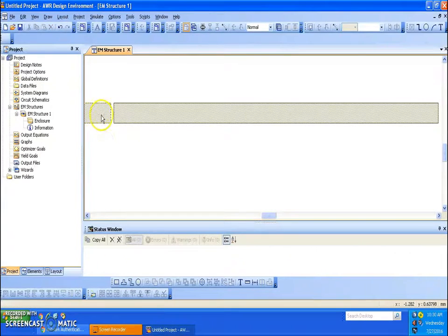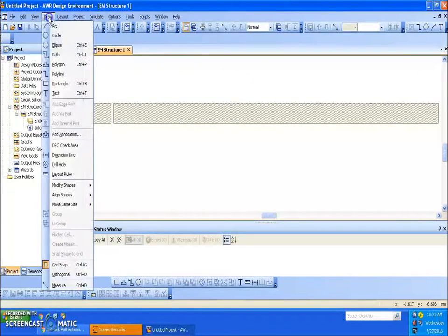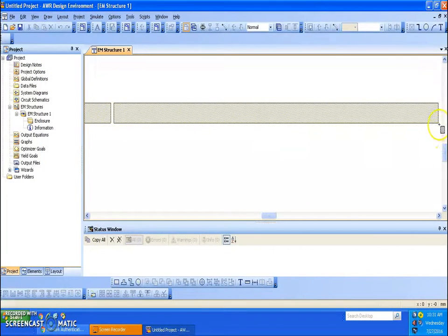The same way you need to add another strip line at the other end of the microstrip that you have drawn. To fix the feed line at the other end, again go to the draw option and choose the rectangle. Once you have chosen the rectangle, you need to give a space of 0.3 mm at the right edge of the strip.